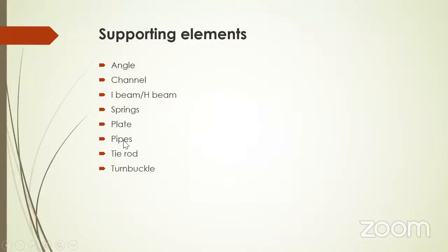And then pipes, like Trunnion support, dummy support, and guide support, will go for this kind of pipe, because these are all ready-made items which are readily available. If you go for a special item, it may cost you more, and the fabrication time and finally your project time will also go high. These are all ready-made. While designing the pipe support, we have to think these are all the items we have, and accordingly we have to design the piping support or fabrication drawings.